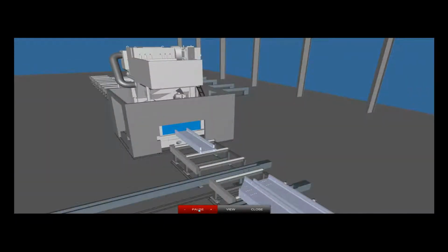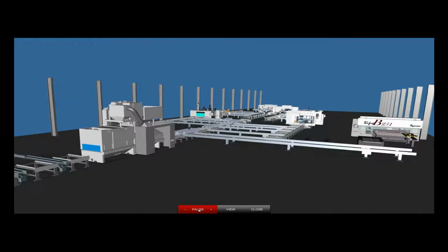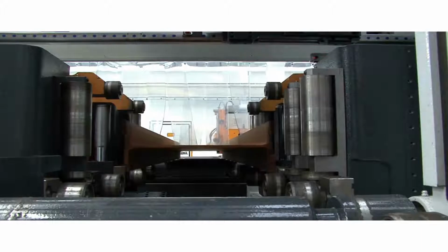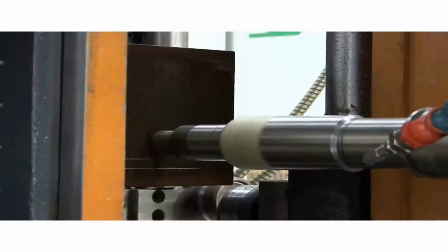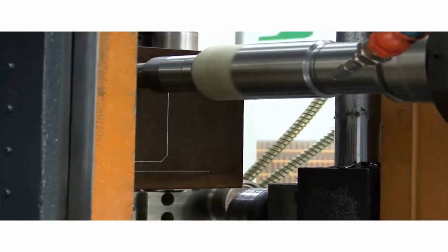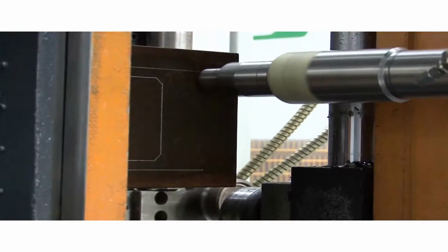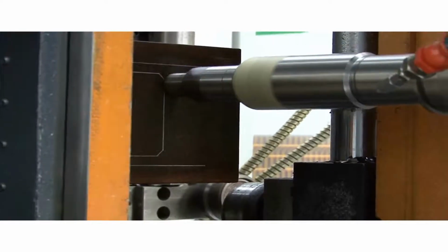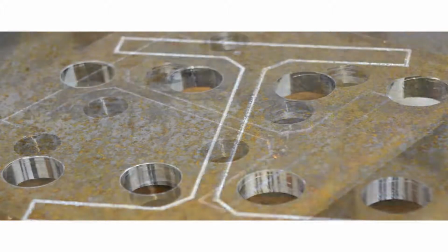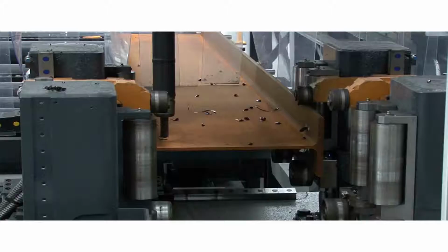If you have one or two machines, the process is exactly the same. Okay, so the machines themselves, let's take a look a little bit more in depth on the machines. So of course you have machines then for drilling, stamping, this is what we call the layout marking. So the information of how those pieces fit together is driven directly from the Tekla model, so the machine knows how to actually scribe those pieces and show the fit up. Again, all the drilling information, layout, simple enough so you can see exactly how that fits together.